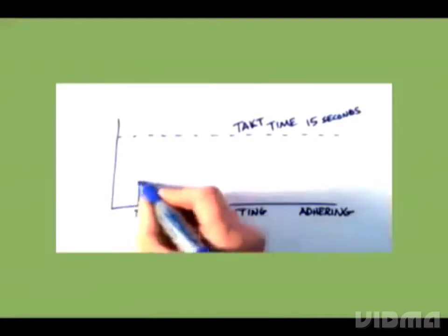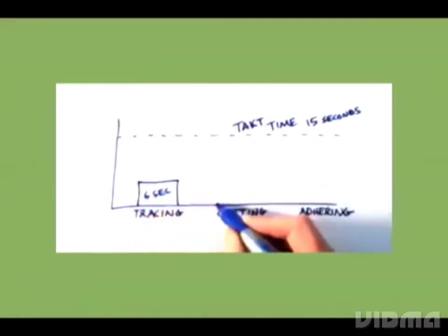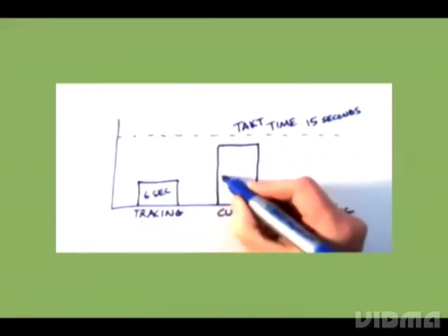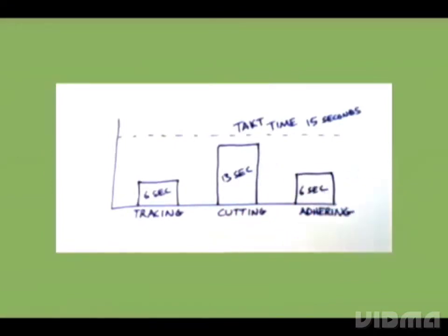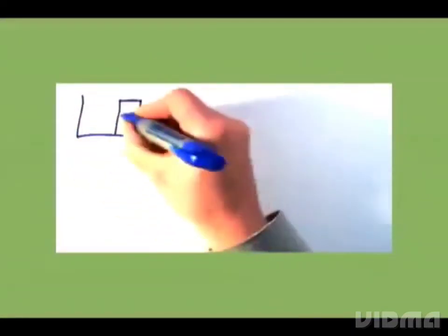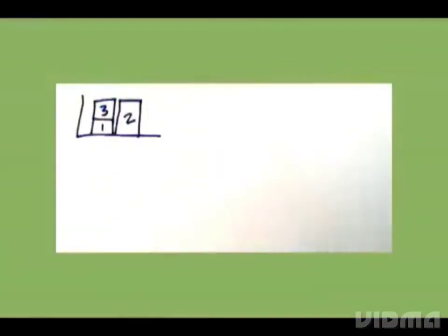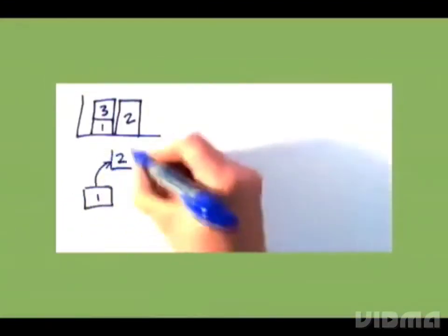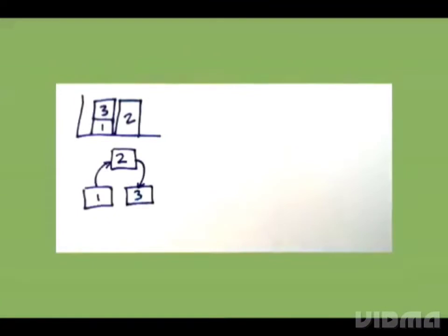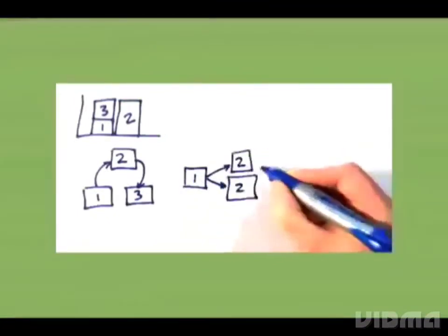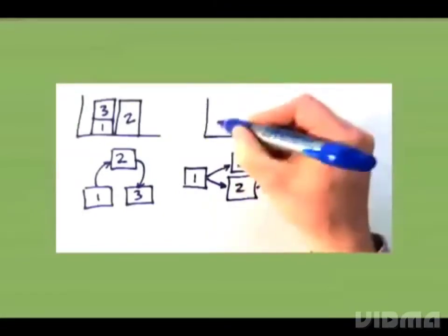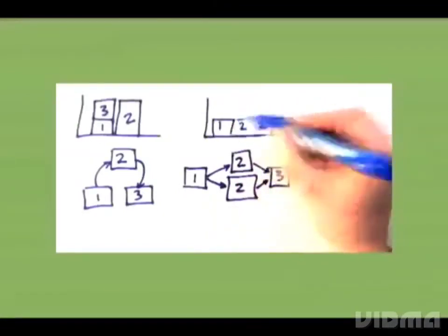Correct, 15 seconds. Even though cutting is slower, it is still meeting our takt time. So as a whole, the process is meeting takt time. Looking at the timings of each step, are there ways to improve this process? Sure. The first and last step could be combined and still meet takt time. Another option would be to have 2 cutters, which could bring the overall process cycle time down to 6 seconds. In this scenario, the additional speed is not required, so the first option might be preferable.